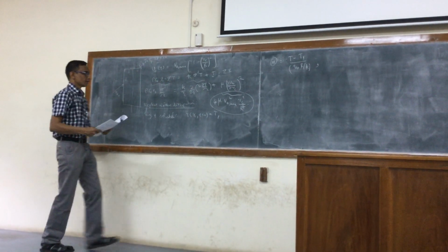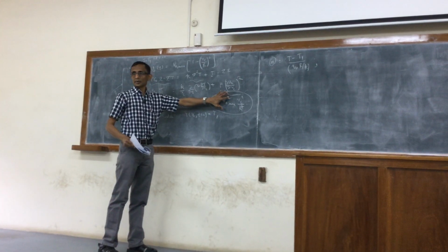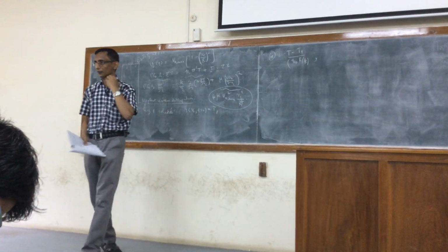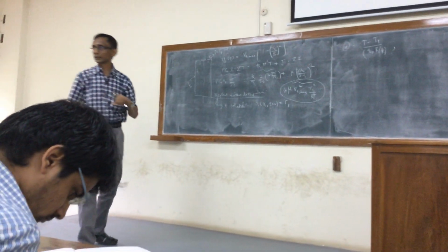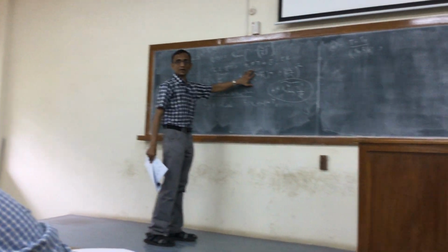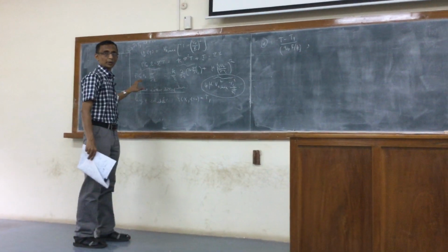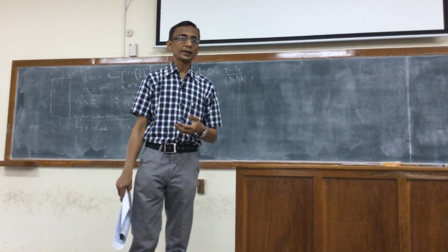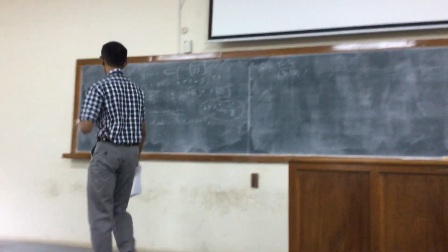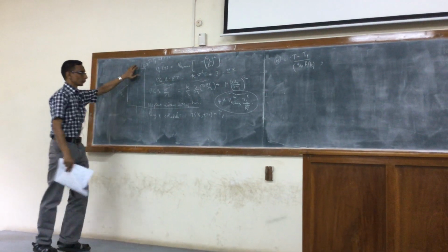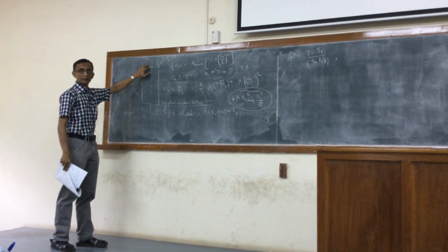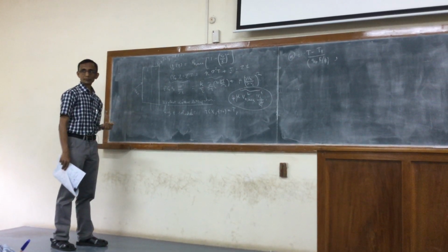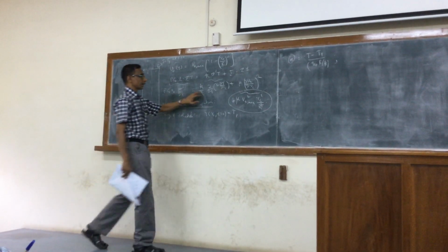That's one, because inclusion or omission of this term is not going to affect the boundary condition. Neglecting the axial conduction term will affect it. When you neglect the axial conduction term, which we have done, you need only one condition, considering a very long cylinder. Otherwise, we would have another boundary condition at Z equal to some length. So consider neglecting that.